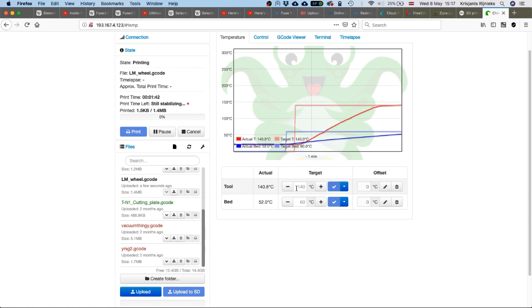You can use only one material. This is a single extruder, but there are also printers with multiple extruders, which are able to print support material or different colors at the same time. But here all of the printers that we have are single nozzles, and we generally use PLA. For rapid prototyping, it's just enough, unless there's a project that is rather experimental, then we can try to experiment with different filaments. But in most cases, like 95% of the cases, PLA is just fine.